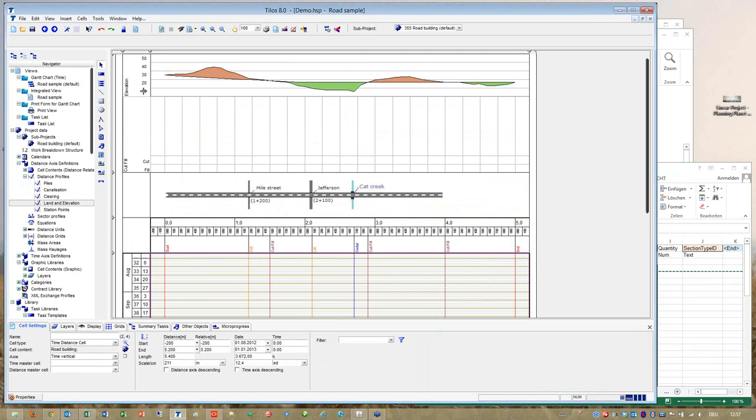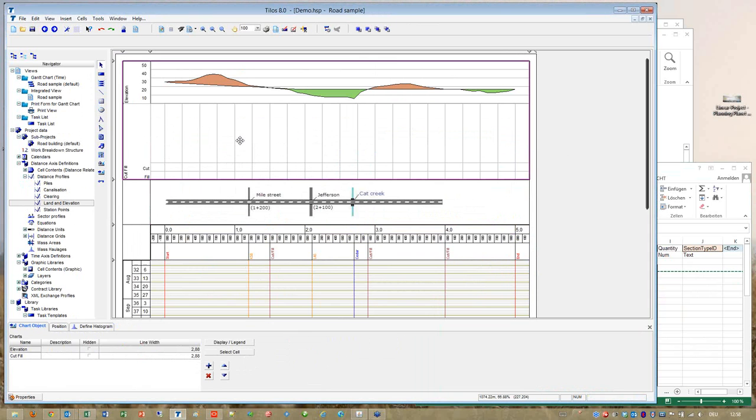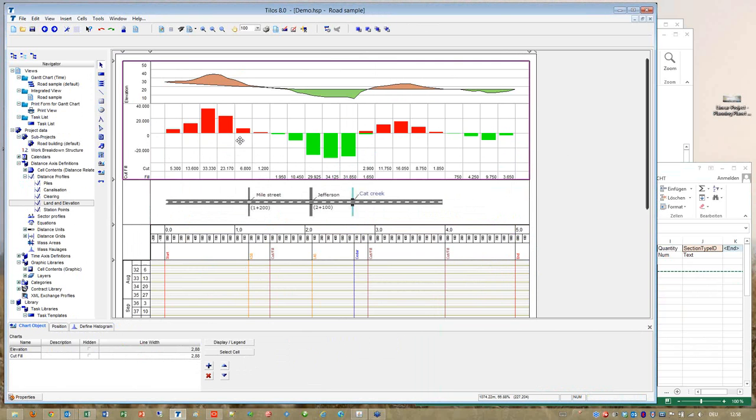This elevation profile draws a diagram, coloring the different sections differently, like here there is cut and here is fill. We check which line is over the other, and by this we decide the coloring. We do not only generate a picture, we are also creating a diagram giving the exact quantities in this section here.